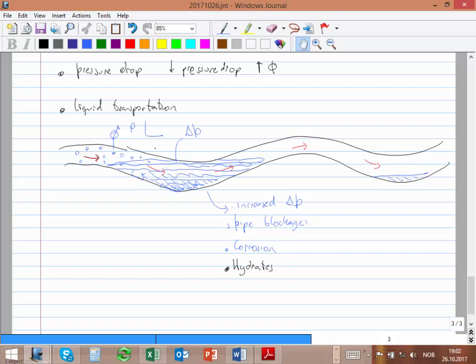Okay. So that pressure due to the plug is going to increase until it is high enough and then pushes the whole liquid, and that becomes like a slug. It's going to travel like multi-phase flow. It's going to travel as a slug, and then the separator, remember, the separator has a control. The separator, in order to operate happily, has a level, like I told you, and a pressure, and then both go to these valves that you have here. And that's fine, that's how it keeps the pressure constant.